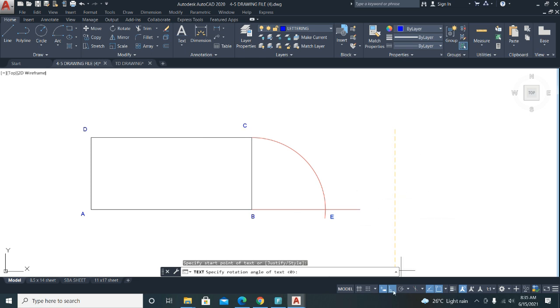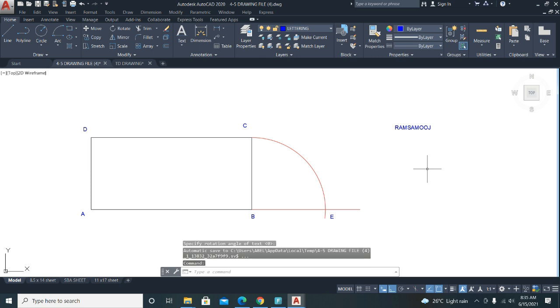Make sure the auto mode is on so that you are staying horizontal, vertical, left and right. Now pull it down and just press enter. Right? And now you can type in accordingly what you want. Okay, for example, all right, then click outside and press enter to complete the command. Okay, don't need this, I'll delete it.